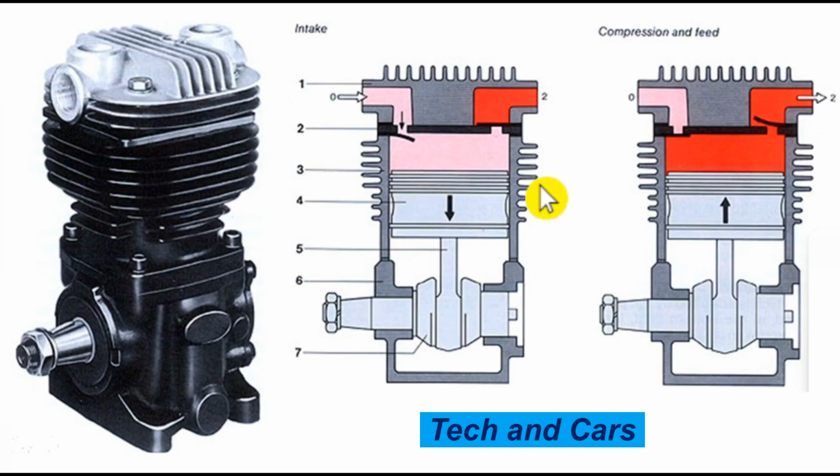And when it comes to cooling, see these fins on the cylinder and on the cylinder head, those are there to dissipate any heat that will be generated. As air is compressed, the pressure will increase, and so does the temperature. That increased temperature has to be removed. Removal of the heat from the compressor is done by the fins conducting it to the wind that is blowing over the air compressor. So simply speaking, this is how the air compressor operates. The air compressor must be cooled by either the engine fan or other means of cooling. It is usually air cooled, as you can see.